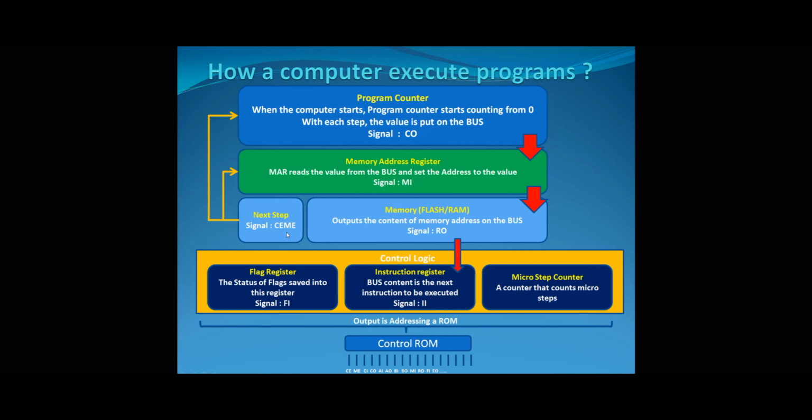However, if you remember, we also had the memory address register, which was again a 16-bit binary counter, and therefore we kind of need to keep those in sync, at least at this stage. That's why we are going to do the same thing using the memory enable signal, which basically just steps the memory address register module to the next step.